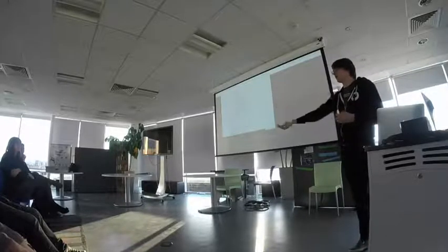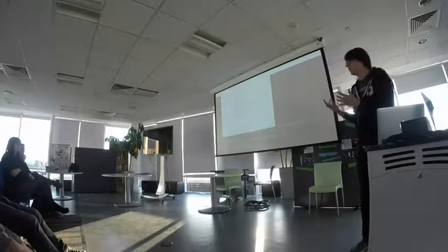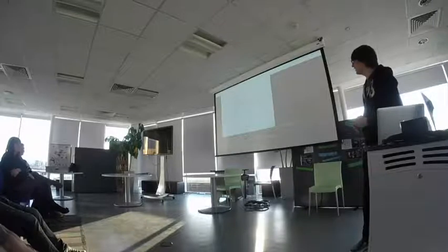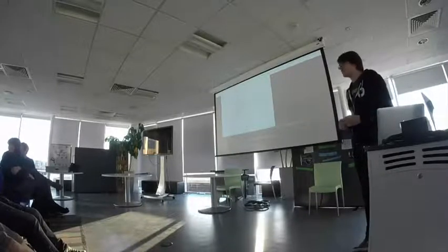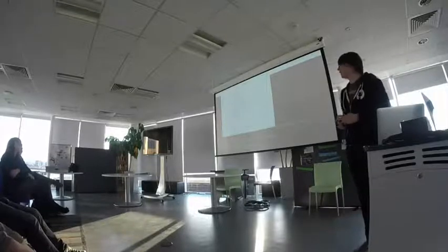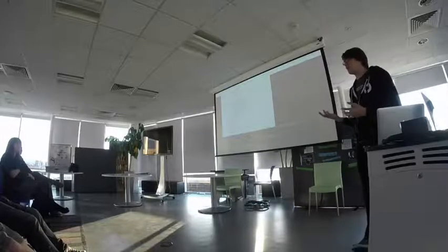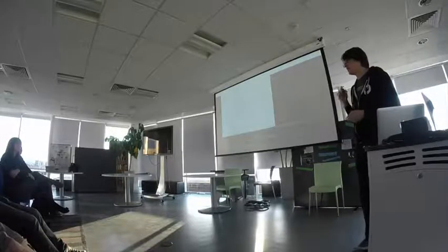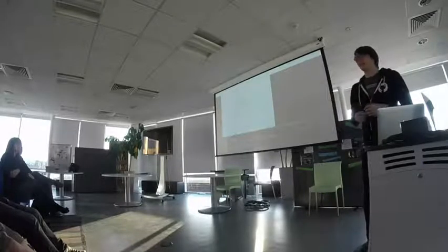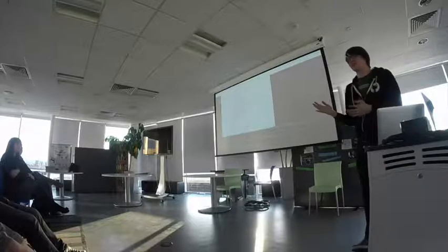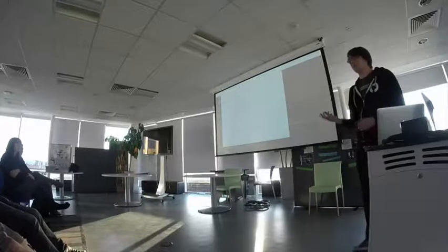Front is forwards, go forwards. Alright. It was written by a German guy, so it's all a little bit broken English occasionally. And some of it maps to the documentation, so there's some slightly strange behaviors in the API. If you want to set a speed, it's between 0 and 1, which is relative to the speed that's set by the iPad app, which is in meters per second. So you kind of go with the defaults usually, because there's no real way to set that by the API.